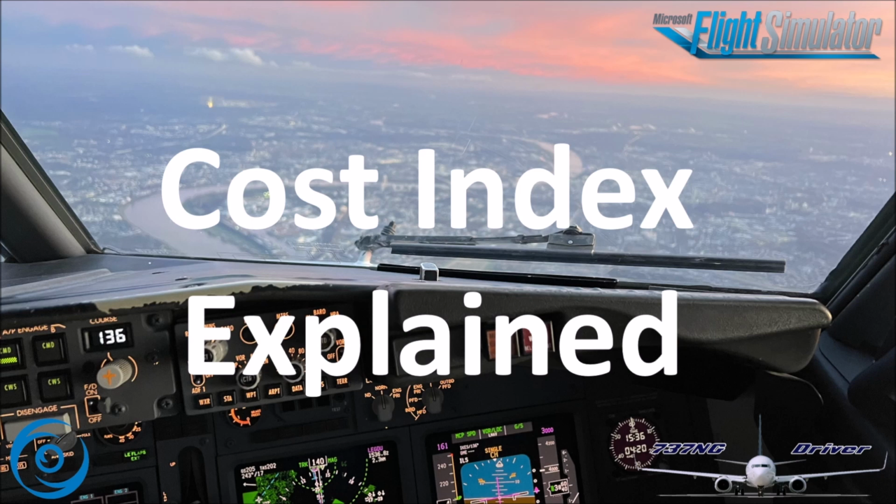So for a typical flight in a Boeing 757 at cost index 0, we're looking at a climb speed of around 290 knots and on conversion Mach 0.778. For cruise it's going to maintain that Mach number, and in the descent it's going to go 250 knots. If we use the highest possible cost index of 9,999, it's going to climb at 345 knots and on conversion Mach 0.847. It's going to maintain that Mach number in the cruise, and then in descent it's going to reduce to Mach 0.819 and 334 knots on conversion.